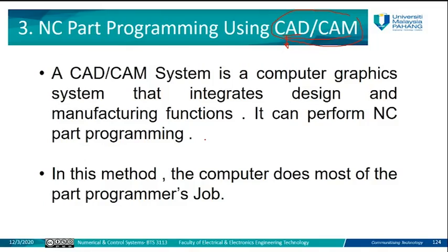In computer assisted, the programmer still has some tasks to do. He develops the program, which is like instructions. He defines the geometry, the points, the circles, the lines, and all this is translated into instructions. These instructions will be fed to the APT. APT will generate the G code. But in the case of CAD/CAM programming, only the designer will work.